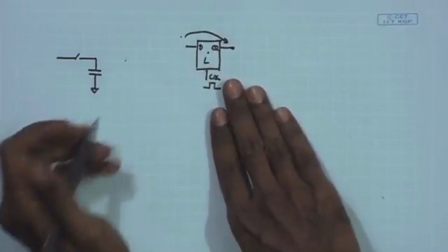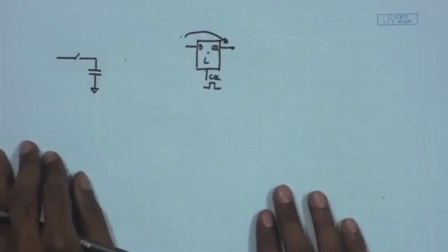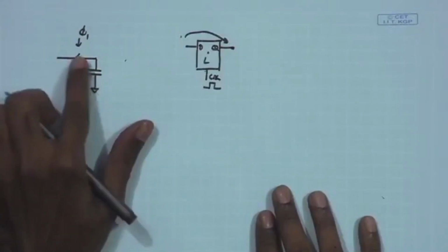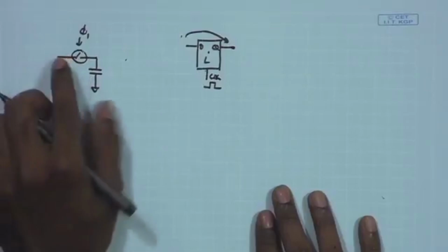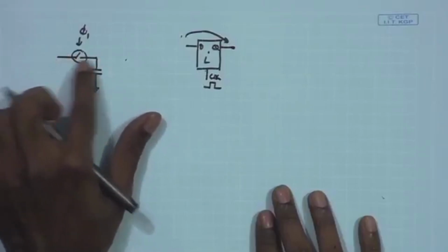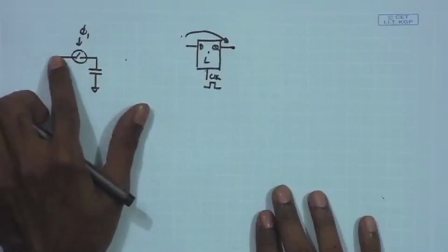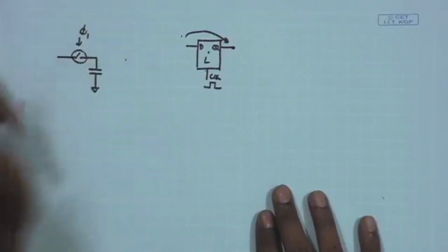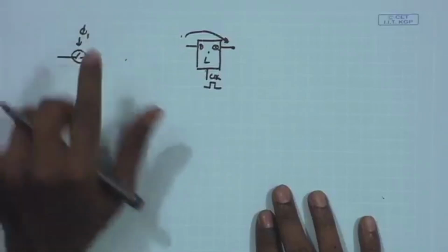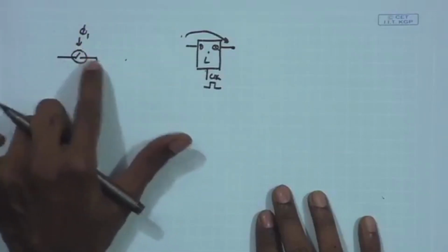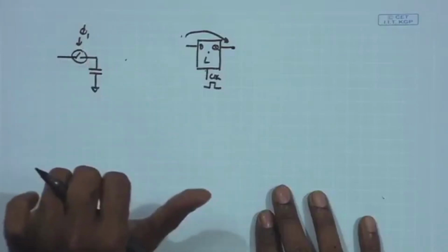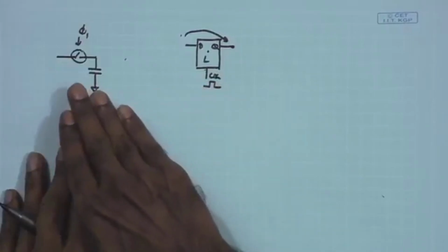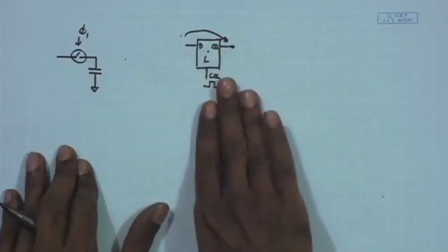It is something analogous to the analog sampling that we have done, right. You have the phi 1 phase which is switching this switch on, and under that condition the switch is transparent, whatever analog value V in is available, it is getting stored on the capacitor, and after that when phi 1 goes low and phi 2 is on, this is disconnected, but this capacitor retains the charge. So, it looks like this latch is doing a function analogous to the sample and hold circuitry, but it is doing it in the digital domain.